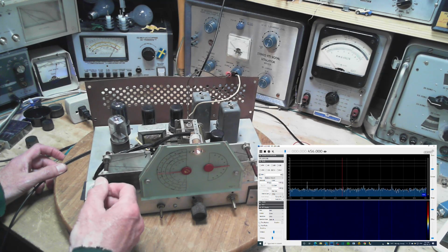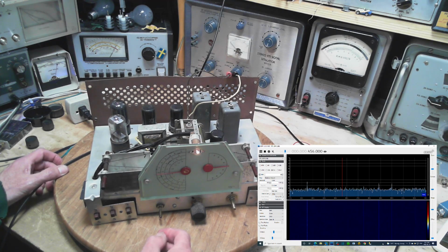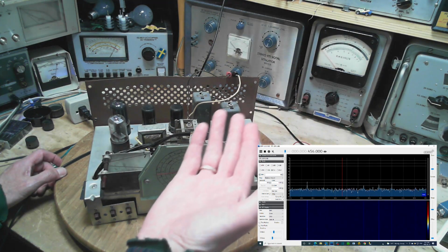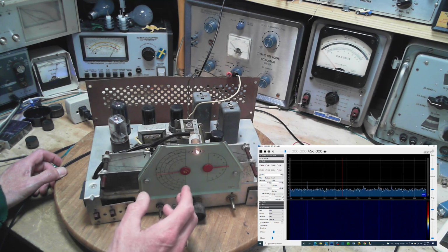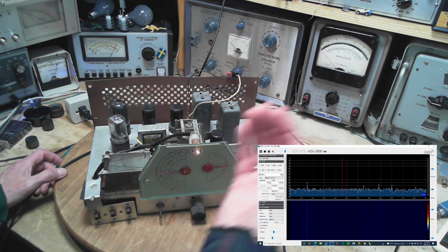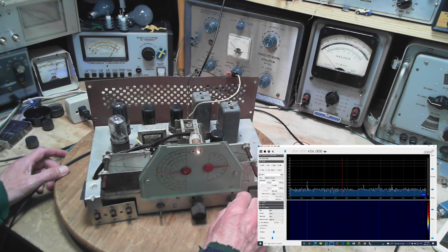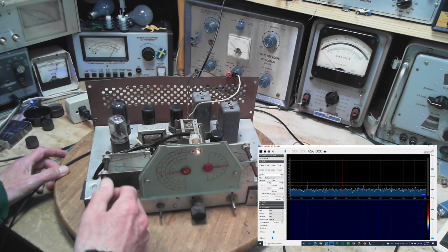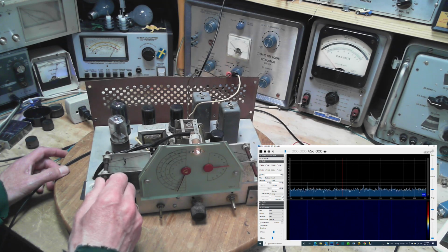But see, that's not necessarily a quiet spot. With these radios, tuning to a quiet spot, you could be tuning to an unmodulated interference signal. There's so many of them in our houses. And it's coming through the radio, and nothing comes out the speaker because it's not modulated, but it causes the AVC to cut the volume way back. In fact, I think these radios seldom run at their full sensitivity because they're constantly encountering some level of noise signal all the way across the band. So I believe. That sounds a little like it.